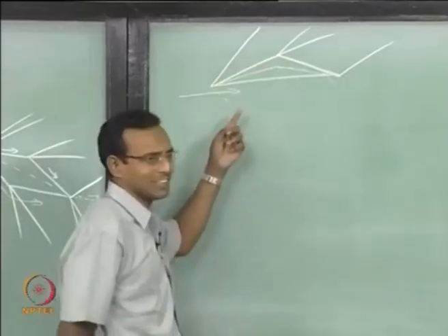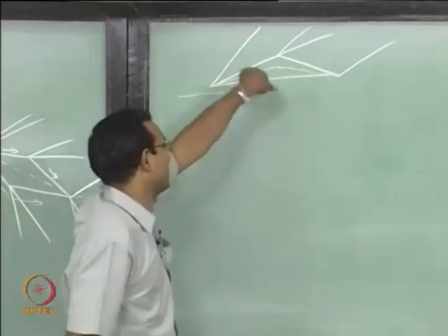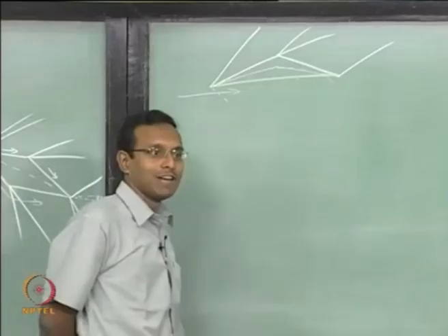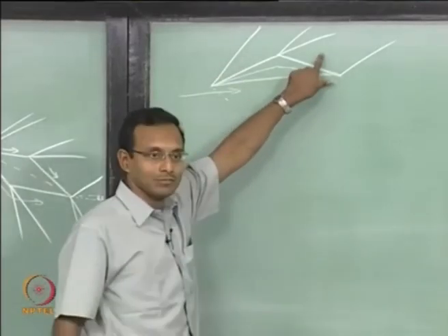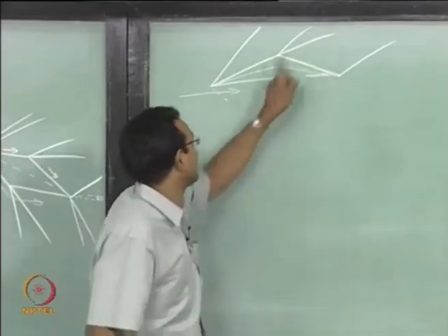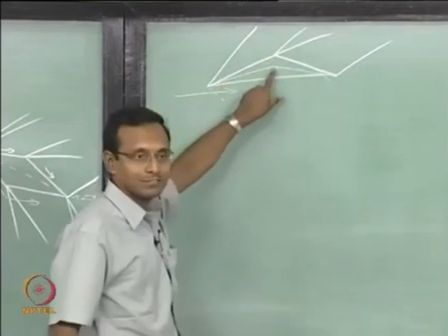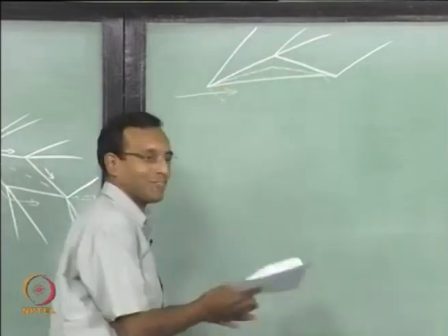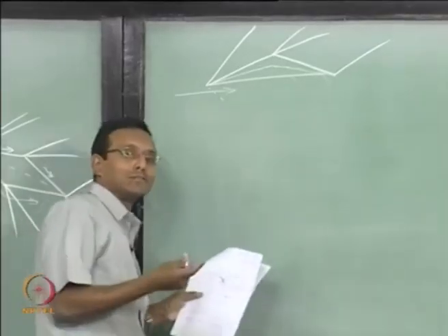That is not the only thing this will have. This will have a huge torque downward. It will have a negative torque on it. It will have a moment on the airfoil, because this pressure is high, this is some middle, this is low. So this force will be like this, this force will be like this. Overall, it is going to have a torque around the center. It is not a good airfoil to use in any aircraft, but this kind of flow field you have to get used to solving.